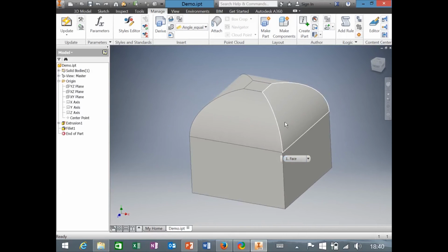But basically what it'll do is it'll pop up a dialog box telling you that it failed to solve some component of your model. That can be due to various different reasons. Usually it's due to some feature that you based a design on somewhere in your hierarchy being no longer available. So for example, if you have two lines that were intersecting as a result of some dimension, and you change that dimension so they're no longer intersecting, and you would use the point of their intersection to define some other feature, then it would break.